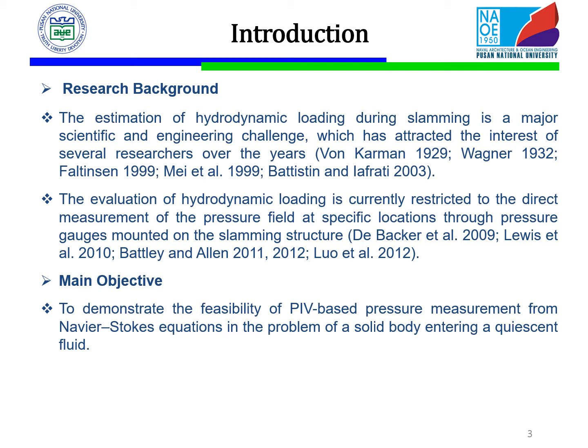The technical advancements in high-speed and high-resolution image acquisition have enabled the use of particle image velocimetry records to indirectly measure the hydrodynamic pressures. The main objective of this study is to demonstrate the feasibility of PIV-based pressure measurements from Navier-Stokes equations in the problem of a solid body entering a quiescent fluid.